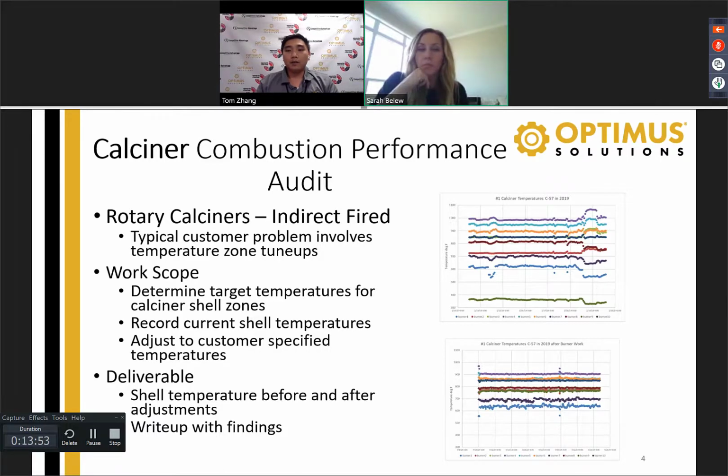So the tighter it is, the more consistent the temperature from the shell to the material. So let's say the customer wants the temperature to be 800 degrees on the shell. The cooking temperature of your material for the chemical change may be 600 degrees. So if we get it at 800 degrees, by the time the heat gets to the shell and gets to the material, it'll be good enough to do what the customer wants, which is a chemical reaction or some part of the process they want.